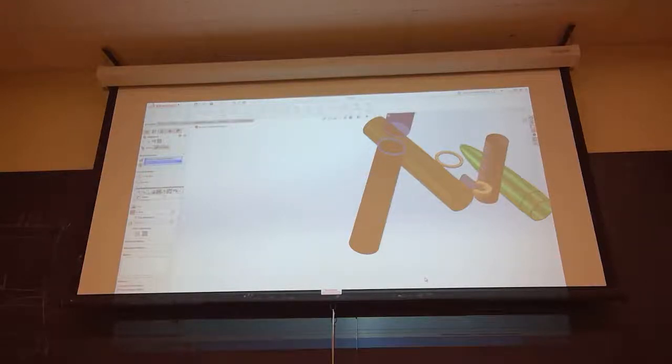So you want to change this, right? Coincident is basically a distance mate where your distance is zero. And we want this to be like 6 inches in. So click this one, and you change it to 6 inches. Rotate, yeah, so that's the middle.